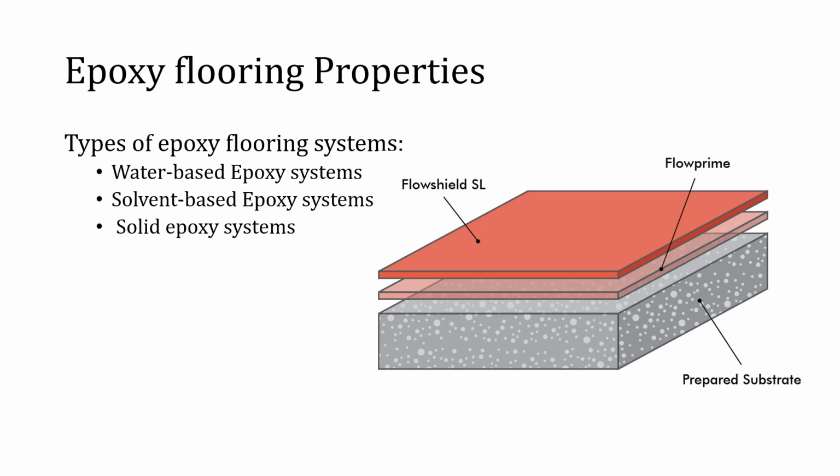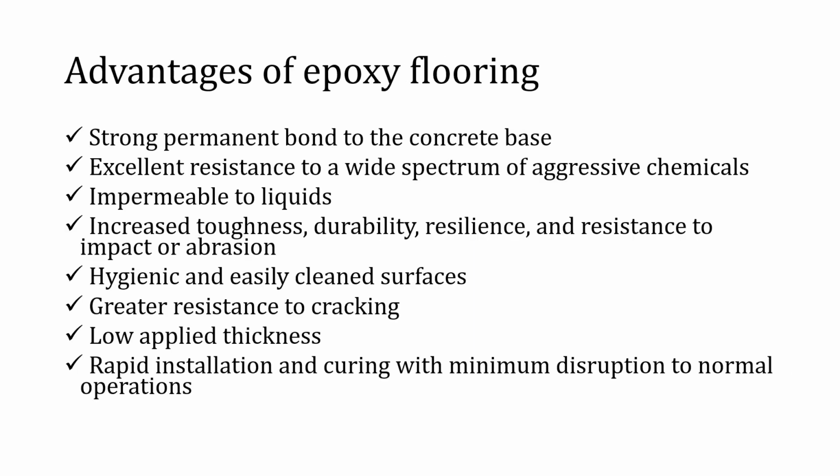The finished flooring should be cured according to the manufacturer's instructions. These generally require 1 to 3 days at 15 to 20 centigrade before allowing significant use by traffic, and 3 to 7 days at 15 to 20 centigrade before wet cleaning, allowing contact with chemicals or heavy trafficking. Adequate curing should always be allowed before wet testing the flooring for drainage or ponding. Epoxy floors are a good option for a variety of industrial and chemical environments, offering both aesthetic and performance benefits.